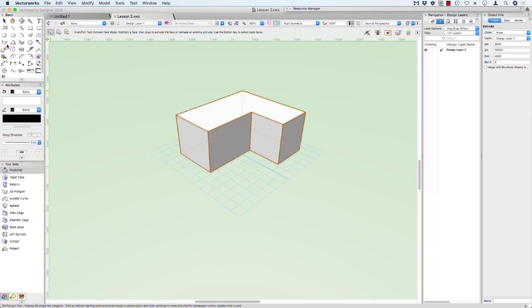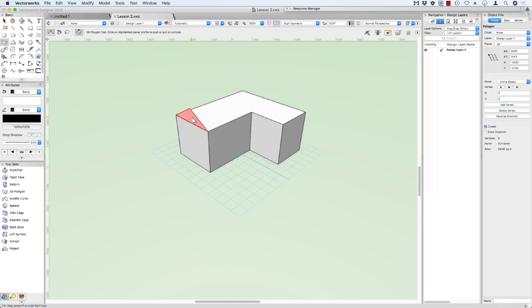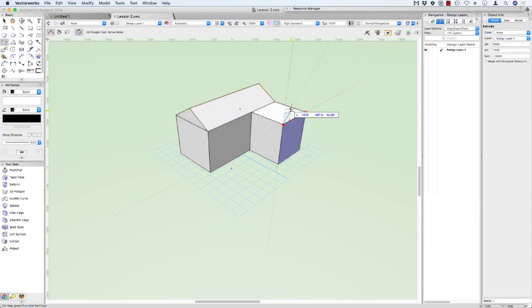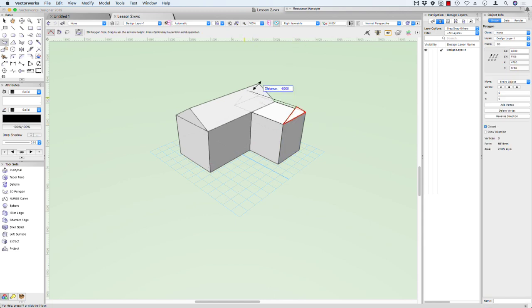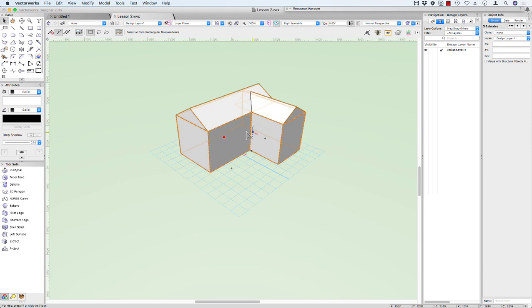And then we're going to build the roof. We're building the roof the same way we have with all the other ones. We've got our automatic working plane turned on. So I'm going to come up at 30 degrees, find the midpoint here, and down to there, across to there, and pull that down to this corner here. So there, touch the midpoint, 30 degrees, there, come across, and pull that back. And then I can select all of those, right click, add solids, one nice big solid object.